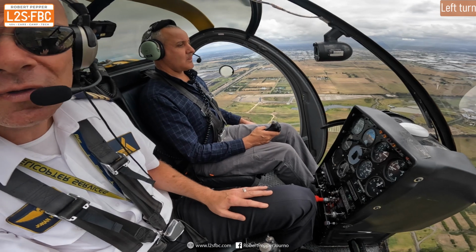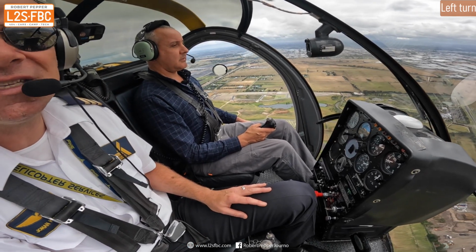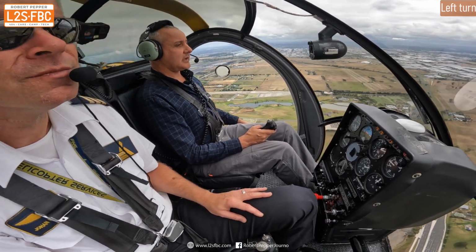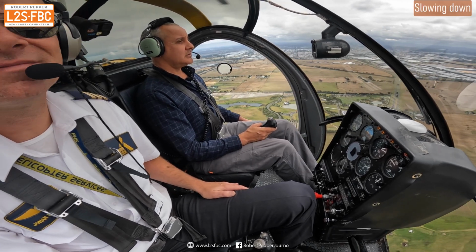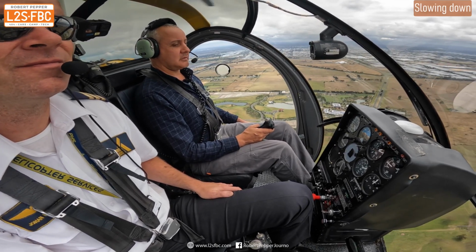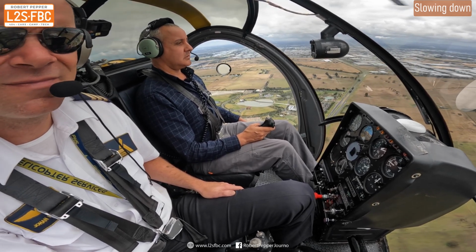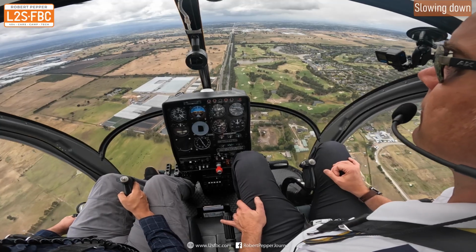So the turns were just a bit of a warm-up, because now things are going to get difficult, and that's because I'm going to slow the helicopter down, and the slower you fly a helicopter, I've discovered, the harder it is to fly. So to do that, we're just going to reduce the collective a bit and bring the cyclic back just a fraction, and of course that's going to mean changes with the rudder pedal, and because that fin on the back isn't as effective now we've slowed down, I'm going to have to work a bit more with the rudder pedals as well.